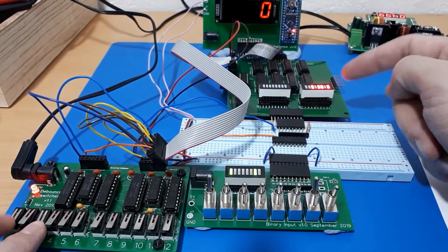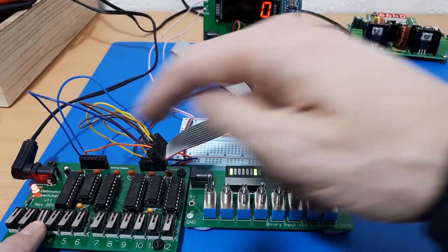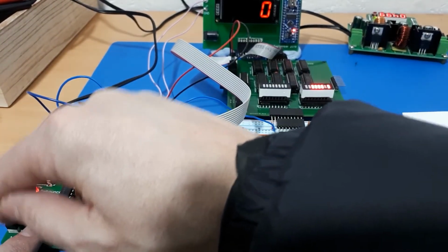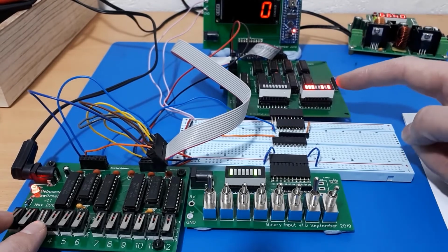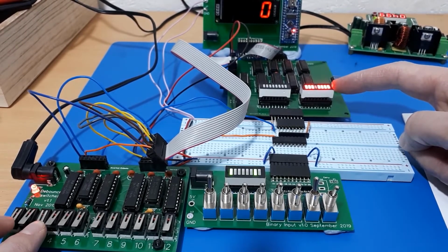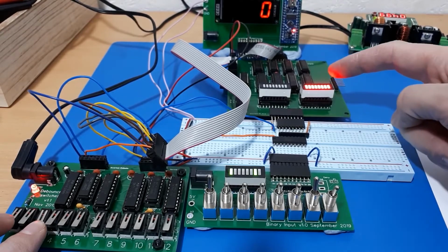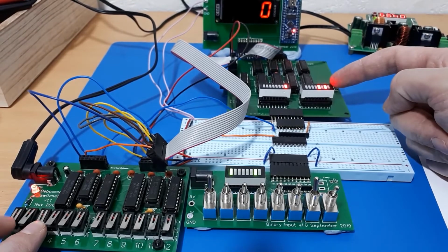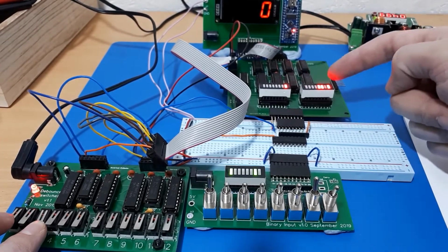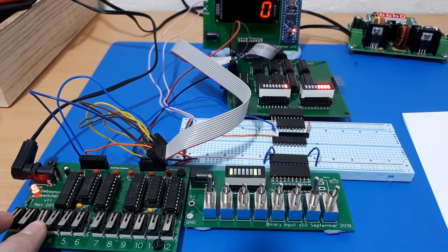but if I sit here tediously pressing this for ages and go all the way up to 256, let's use the other hand for that. Okay, so we're getting up towards 255 now. That's about it. Okay, 254, 255. When we increase by one more, we've increased the high byte of the program counter, and we carry on increasing the low byte. So I've got a value of about 260 or something in the program counter there. And so that seems to work.